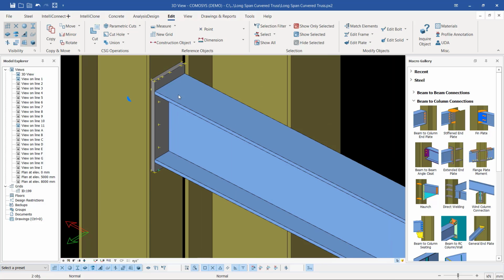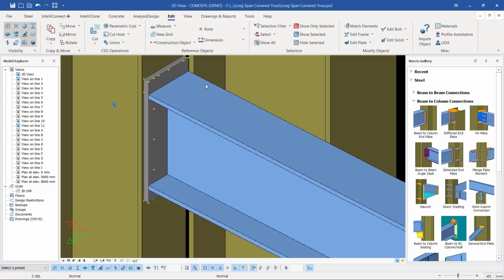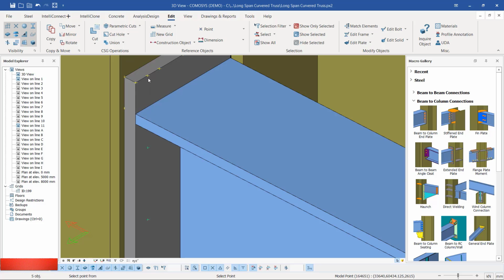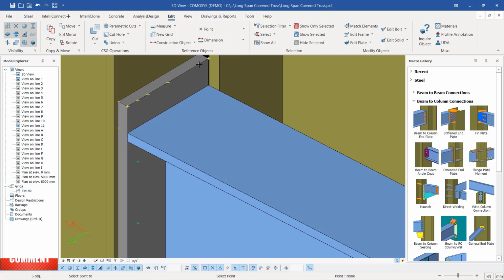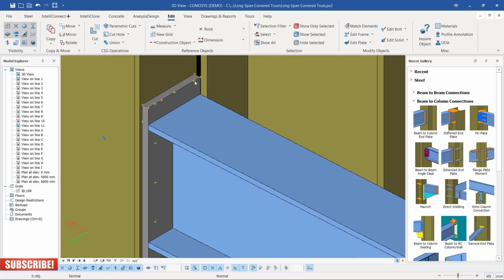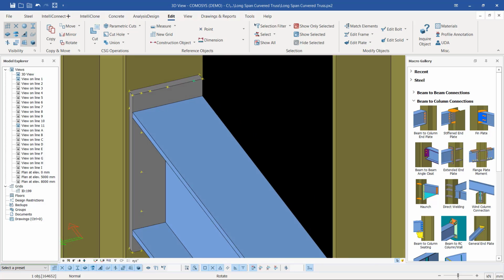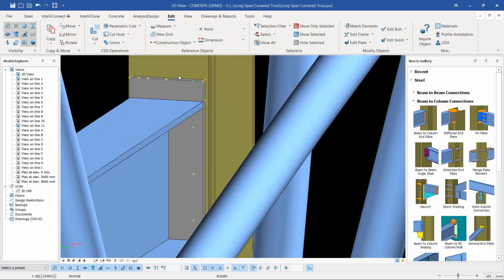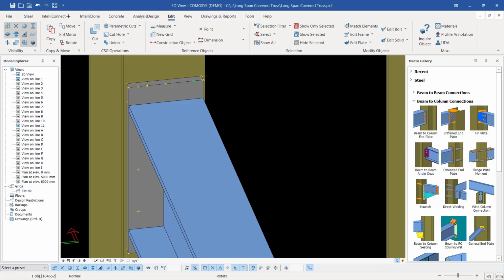And what I'm going to do, I'm going to copy the same points to the other end. So I'm going to select this point, select that point, and select this point here. Then I'll right click and come to copy and pick the 3 points from that point and shift them, or copy them, on the other end. And to confirm that, you can always pick your point of interest and turn the other side. You can see I have the points in location.